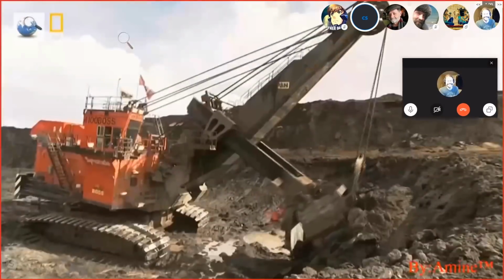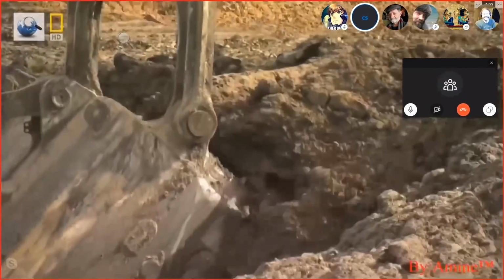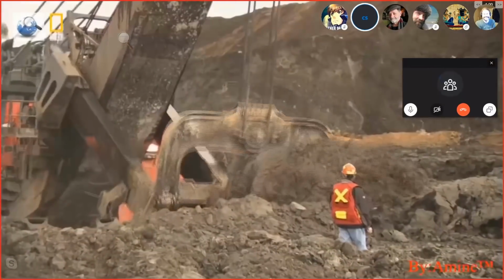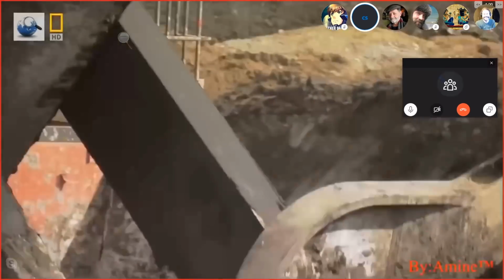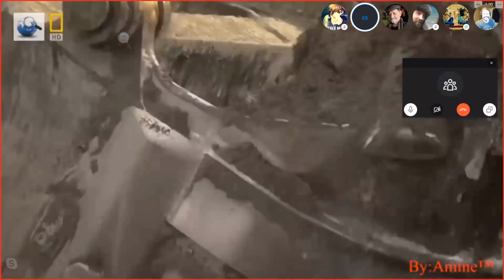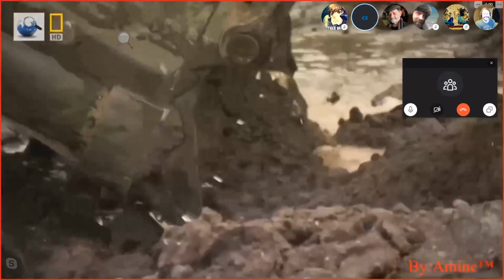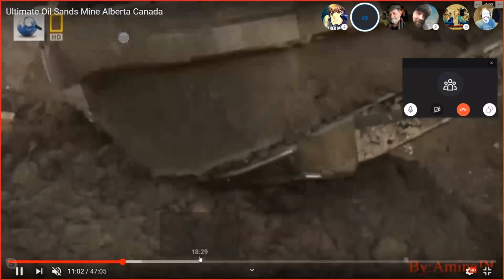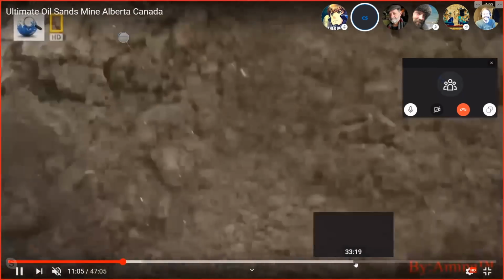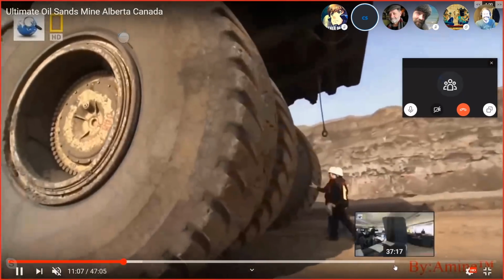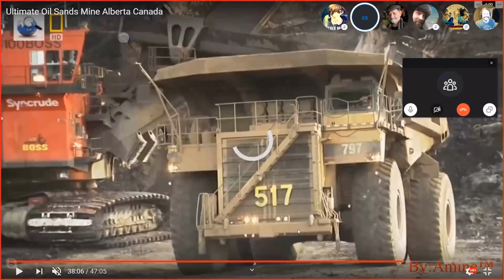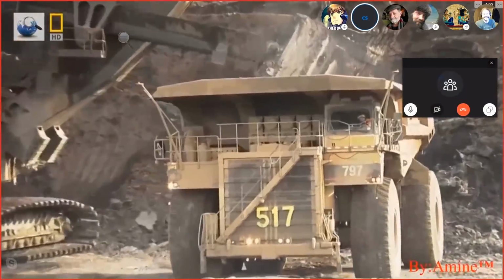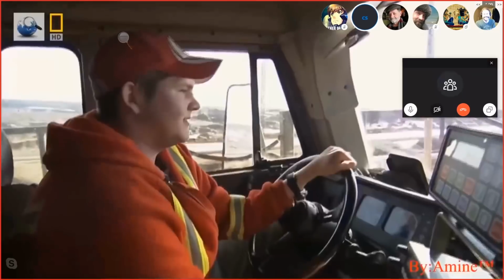What happened was that the bacteria was consuming or eating the shells of the tanks at the iron, which, when you weld stainless steel, at the heat affected zone you'll get like an iron deposit there, so to speak, right? It'll convert some of the iron in the stainless into more of a hematite. Right. But what happened was the bacteria was attracted to the iron, was eating the iron and reducing the sulfur, and then converting that into oil and seeping out through the tank. So the bacteria was turning the stainless steel into oil right before our eyes.